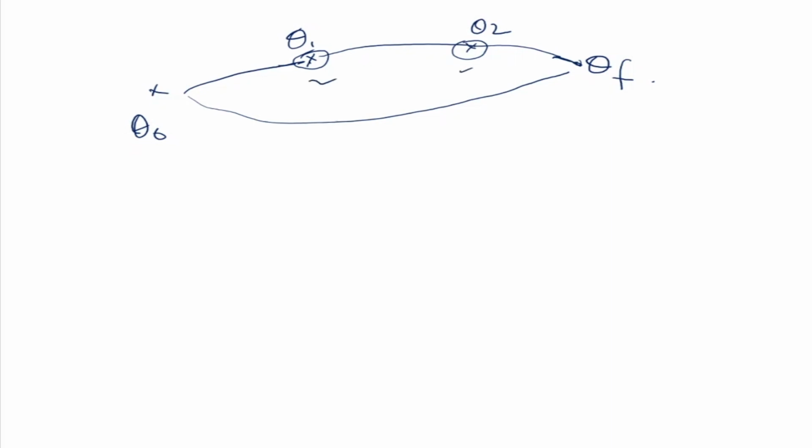Now what is the basic difference? The basic difference is that all three of them are cubic polynomials now. So this is also a cubic, this is also a cubic, and this is also a cubic. All are cubic polynomials. The difference is that at the start point the velocity, theta dot, is equal to 0, and it is also equal to 0 at the final point. But at this point and this point, the velocities are not 0, in order to maintain continuity.